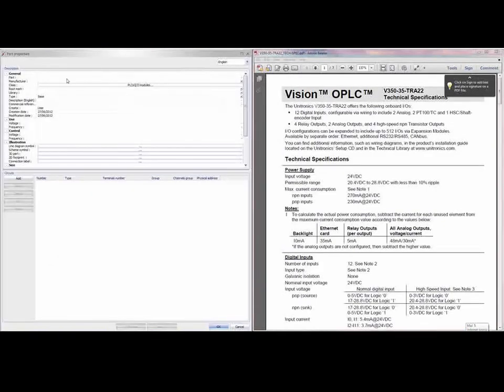We'll just put these side by side with the manufacturer's information, and then we can see what we're actually typing. 350, 35. I can put an overriding root mark, which is basically how the component's going to be numbered, and I can enter a description as to what the component is. So just entering a description there, taken from the technical specification.